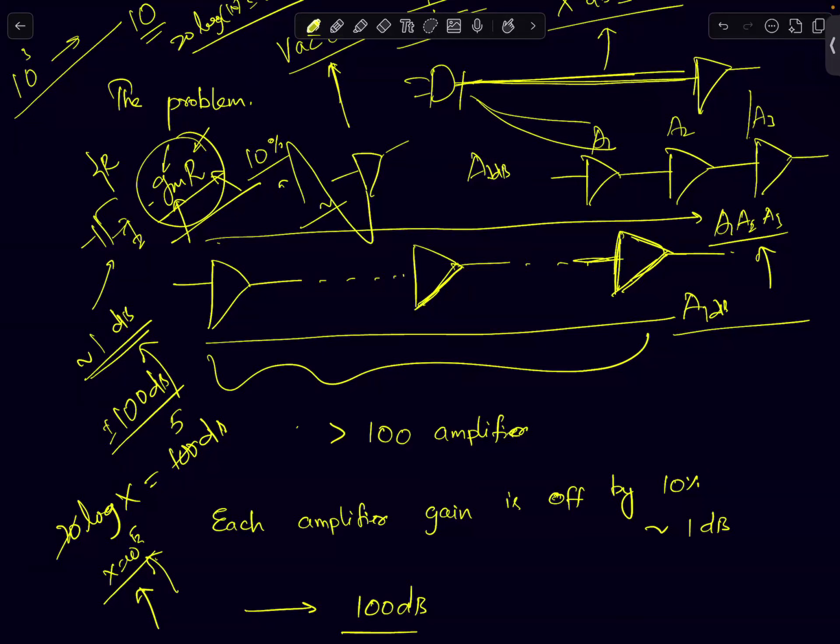We'll not worry about that right now. For you to understand it, think that there is a minimum level for which the signal can be amplified properly, and similarly there is a maximum level for which your amplifier will behave like an amplifier. It will give you perfect amplification, otherwise it's not going to give you the right amplification. So there is a problem of oversaturating the amplifier. If your gain can change by 10 power 5 times, you might end up over amplifying your signal.